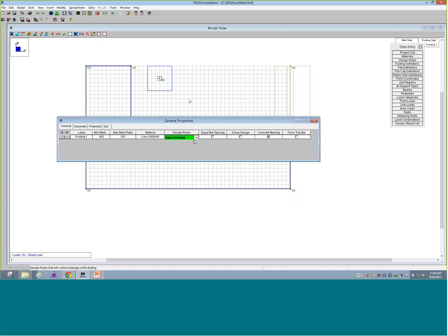The next column we define here in footings is whether we want equal bar spacing or if we want to band them together. So we'll say let's enforce equal bar spacing. The group design: if I have a lot of different footings around our structure, I can tell the program that all of them should be grouped together and designed similarly. Otherwise, each one will be designed separately.